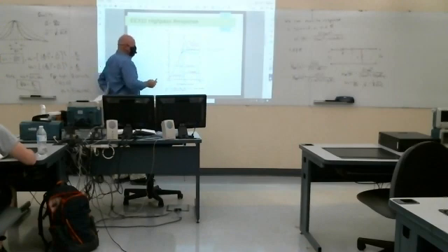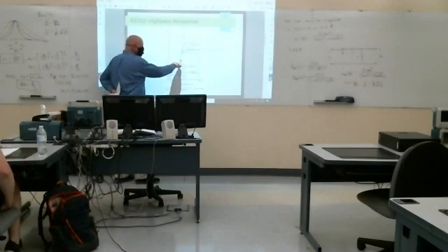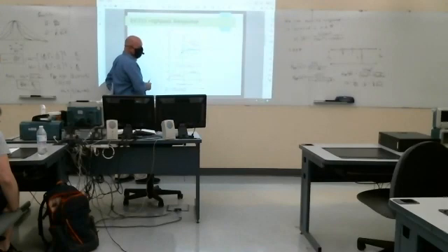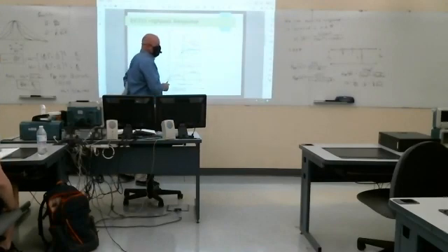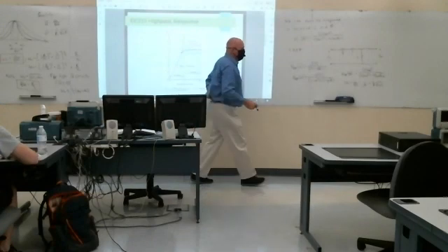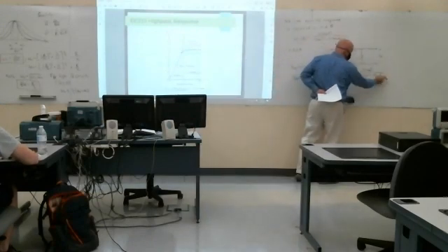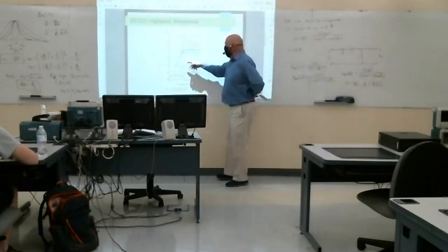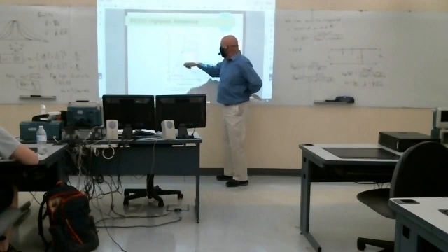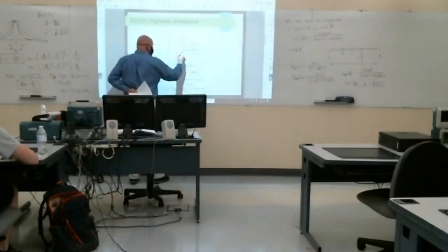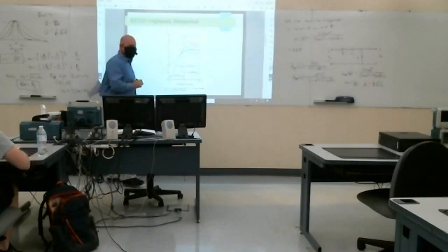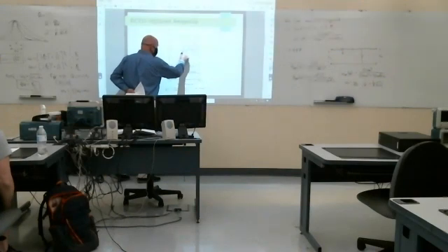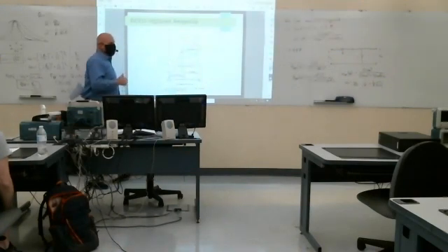So notice here with these second order filters, the slope is 40 dB per decade on this side because it falls off at low frequencies. It falls off as S squared or omega squared. At low frequencies, the 1 would dominate. Whereas a first order high pass would decrease at a slower rate, actually at 20 dB per decade instead of 40 dB per decade. So what about this bump here?